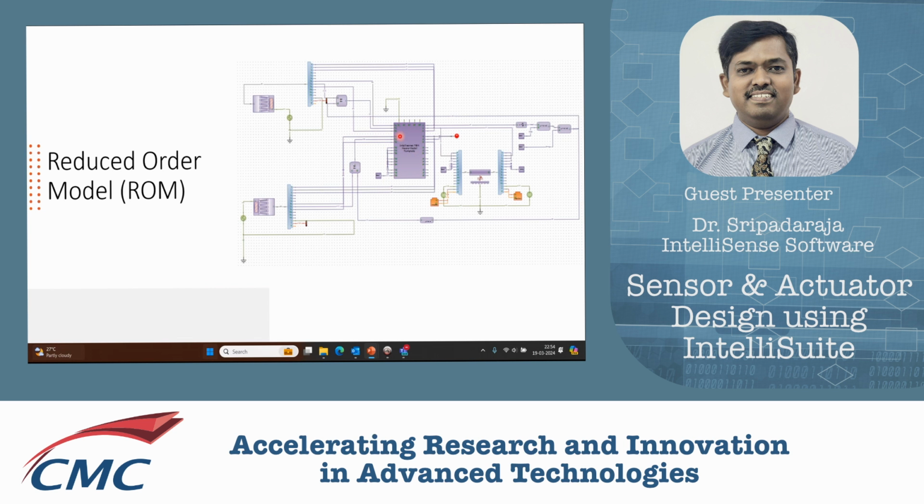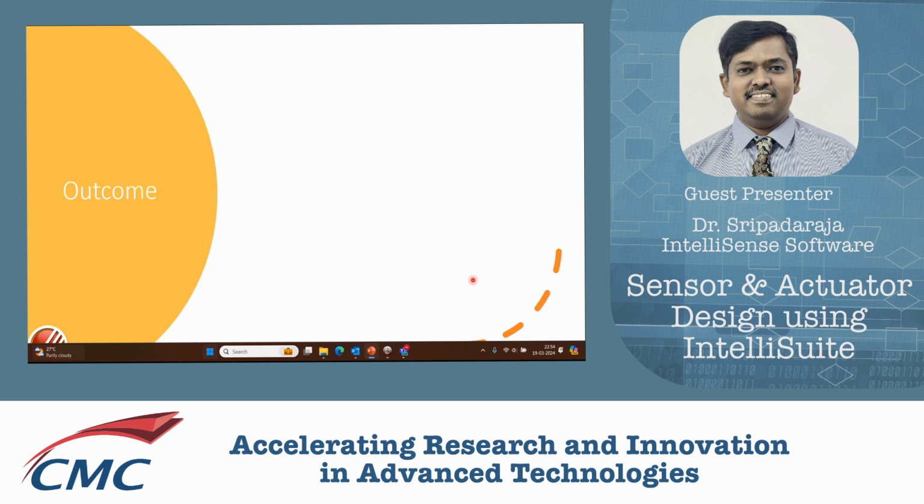So this is just a representation of how a reduced order model simulation would look. This element is called the macro model element, where the HDL file is dumped on this element, and this device works exactly like our FEM model and then throws the output in various signal forms. The signals can further be taken and processed, synthesized, and used to trigger some of the circuits at the subsequent stages.